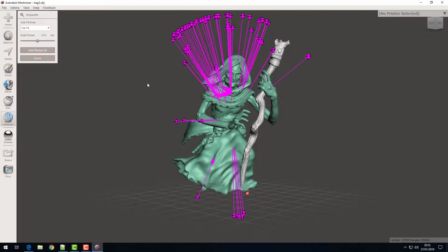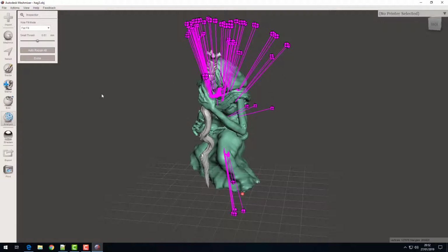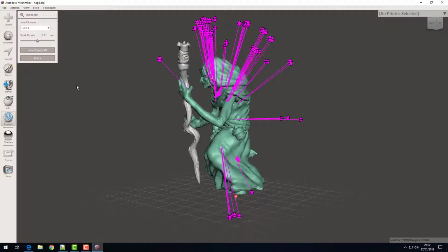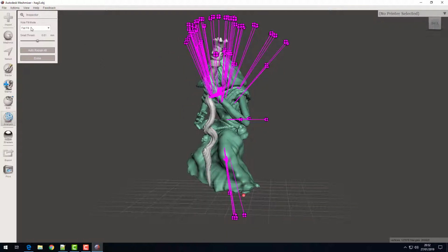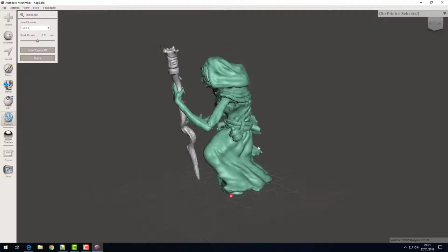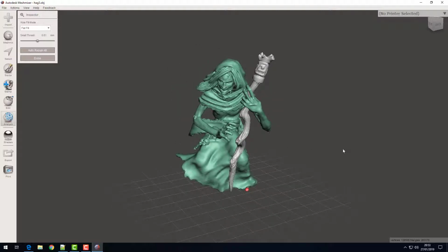In this case, as we do not have holes but only loose parts, we just click Flat Fill and Auto Repair. This bar can be moved to have more or less quantity, but we recommend to leave it at 0.01, which is its base value, and it allows the program to automatically fix and repair. We then click Auto Repair and the object is completely repaired. When an object does not need to be repaired, Inspector points this out by not showing any kind of symbol.